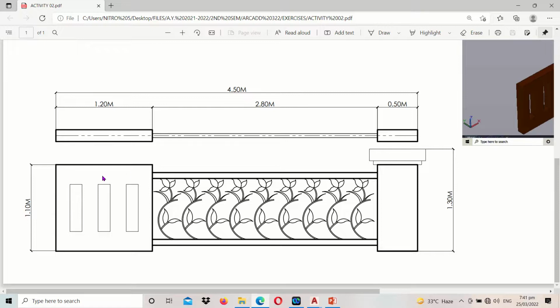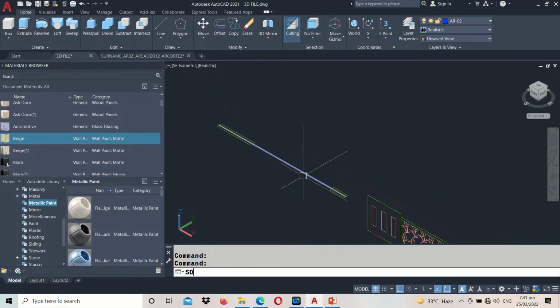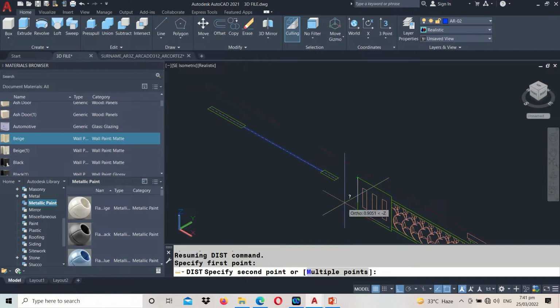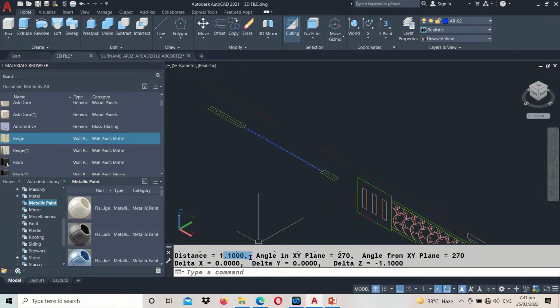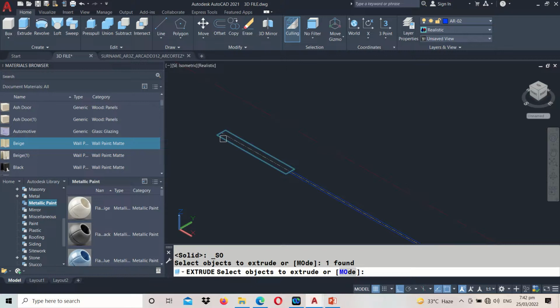Okay, so just the usually have the CHB wall and then the pedestal, and this time we have some floral still works. Okay? So, how to do with that? So, unahin muna natin yung mga ibang elements. Let's go back with CAD. So, dito tayo. Let's check the distance. DI, 1 and 2. That's 1.1. Okay? So, diretso na tayong extrude because this is a closed object naman.